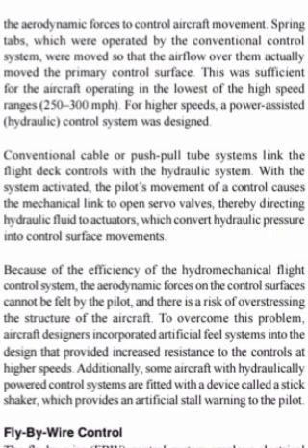Because of the efficiency of the hydromechanical flight control system, the aerodynamic forces on the control surfaces cannot be felt by the pilot, and there is a risk of overstressing the structure of the aircraft. To overcome this problem, aircraft designers incorporated artificial feel systems into the design that provided increased resistance to the controls at higher speeds. Additionally, some aircraft with hydraulically powered control systems are fitted with a device called a stick shaker, which provides an artificial stall warning to the pilot.